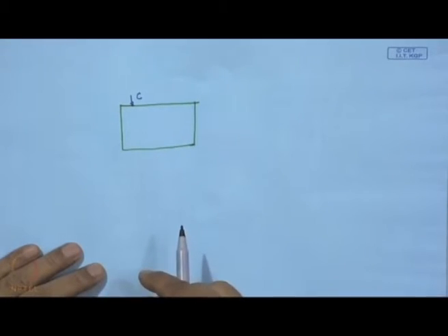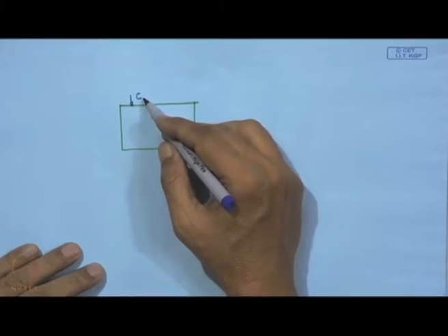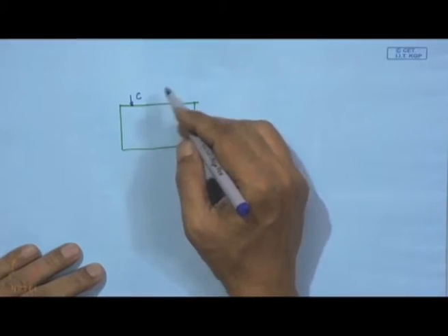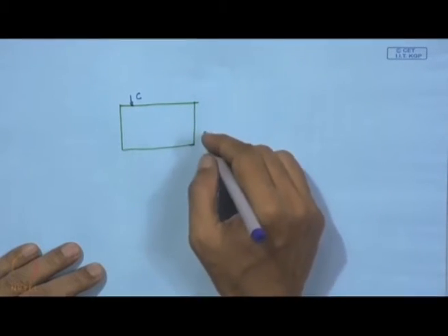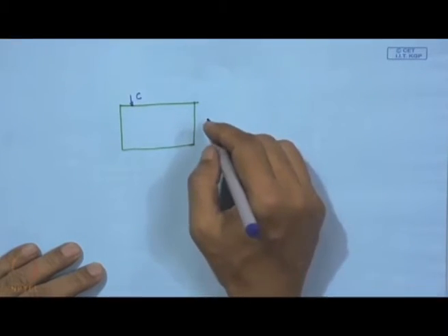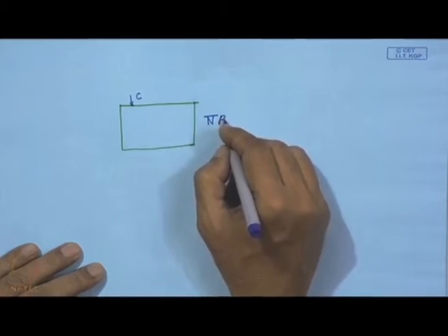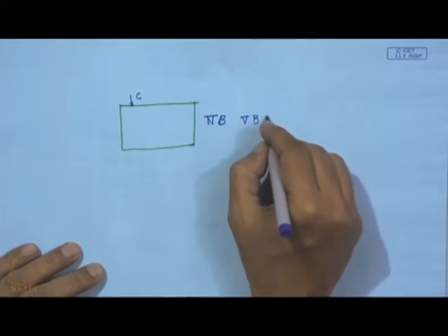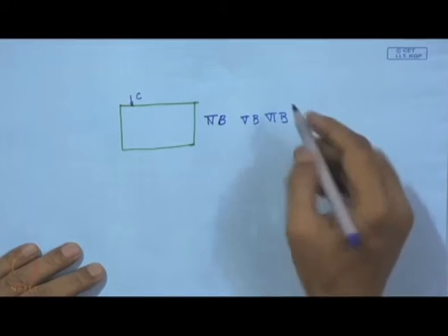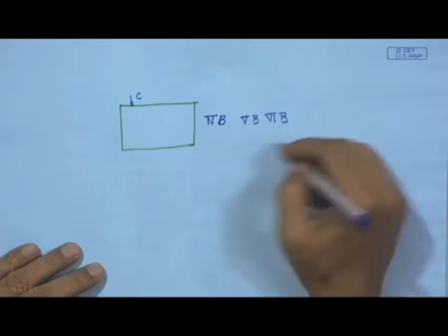Now, in most cases it will be the dissolution of carbon in iron, and once that gets saturated, what is going to happen if this steel has some materials which are carbide formers, say group 4B, 5B and 6B, all this titanium, vanadium, chromium, tungsten, molybdenum, niobium and so on.